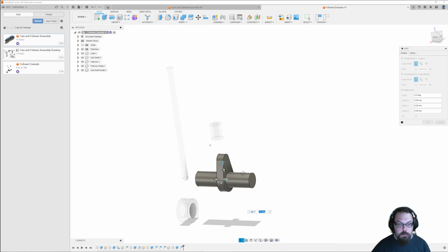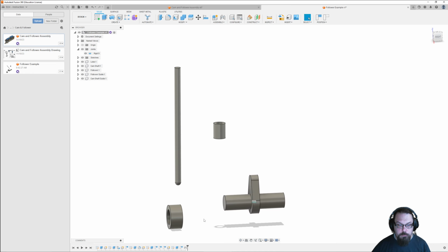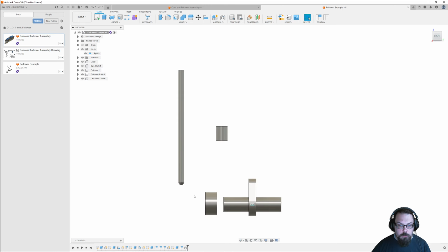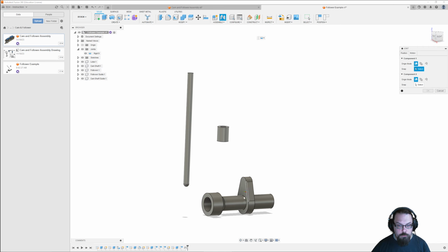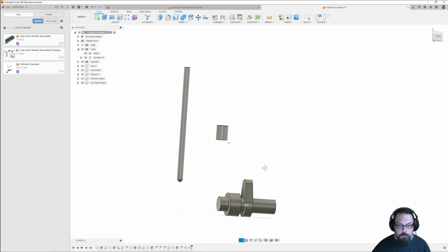And we are going to make a rigid joint relationship between the cam lobe and the camshaft itself. And then we know that we want this camshaft to be able to rotate in a known point in space. So we are going to, again, create another joint that exists between our camshaft guide, and that's going to be a revolute joint. We'll offset this a little bit so we have something to grab when we're animating this.